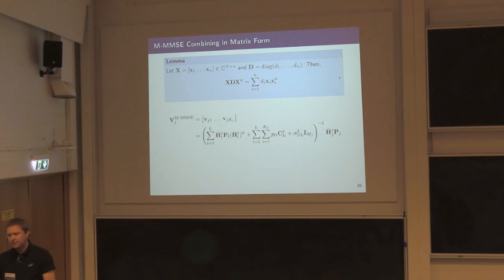How is this compared with the traditional MMSE, where you only whiten the interference part? So that would be essentially the same thing. If one plays around with the matrix inversion lemma, you can see that you get the same kind of behavior.